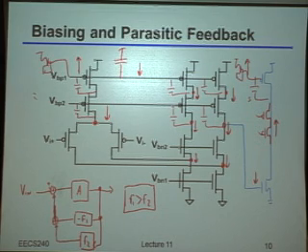By the way, pretty much everything you guys mentioned is a valid potential solution. I just wanted to get to this particular one because, as you can imagine, separating the current mirrors is usually a pretty easy thing to do, okay? So that's usually the default way you would do it. Okay, great. Any other questions on this?